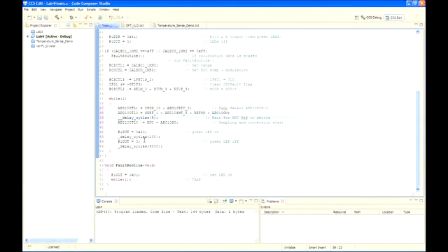That puts us in step 8. When the conversion is complete, the encoder and the reference need to be turned off. The encoder bit must be off in order to change the reference bit. So this is a two-step process. Add the following two lines right after the first delay cycles 100. And that's the ADC10 control 0. That's turning off the encoder, stopping the process, and turning off the reference and turning off the ADC.